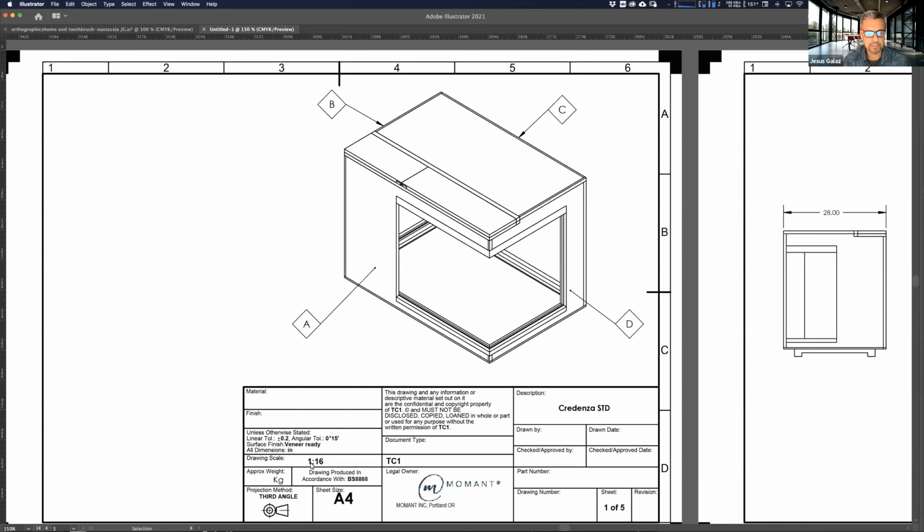So title block, important things are scale, description, how many sheets, sheet size, so you know how to reprint, possibly a coordinate band on either side, top and bottom. Sometimes they're left, right, or left and bottom. Sometimes they're right and top, you see here. This is so that when you're on a phone call with somebody or you just need to refer to a certain section, you can generally say, okay, look at section 4B or something, and you know you're looking in this general area.